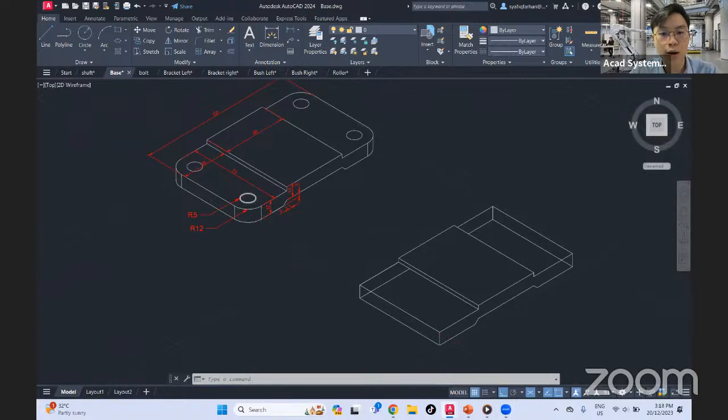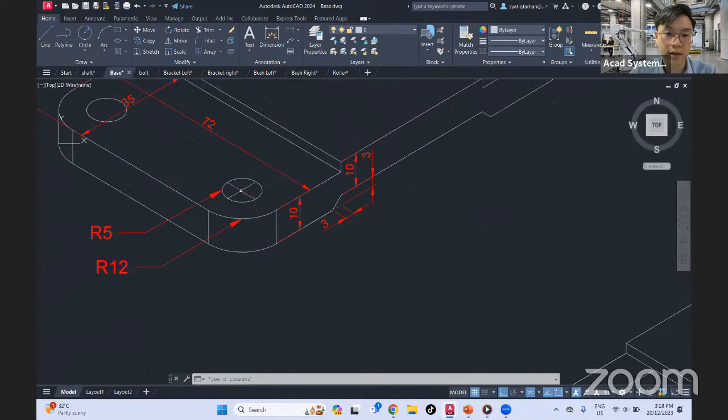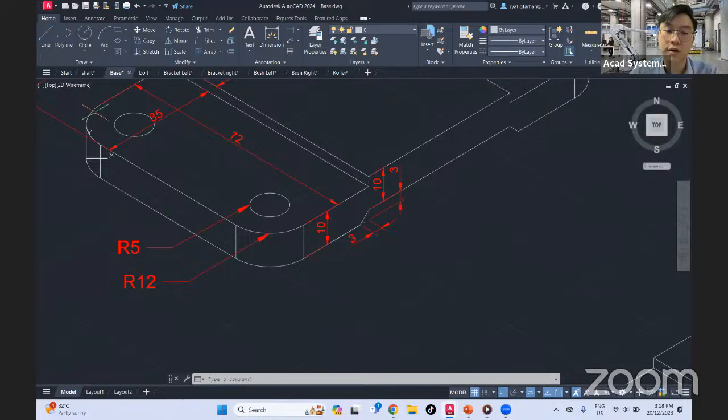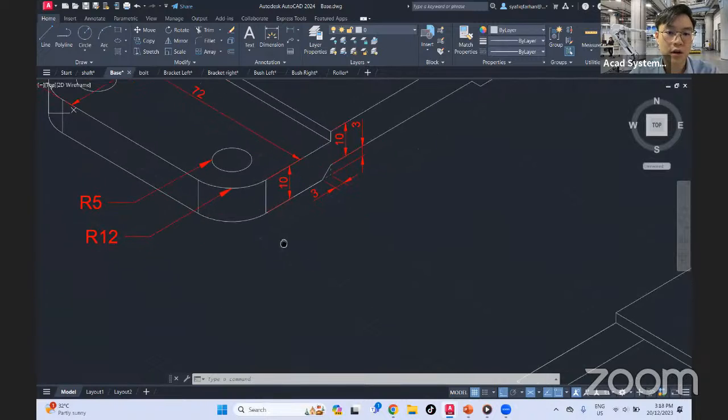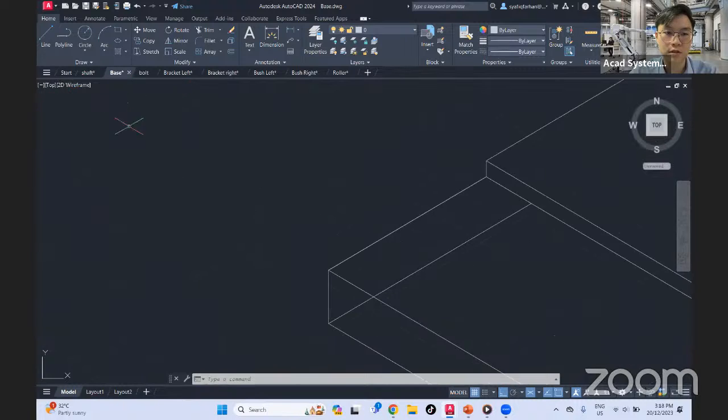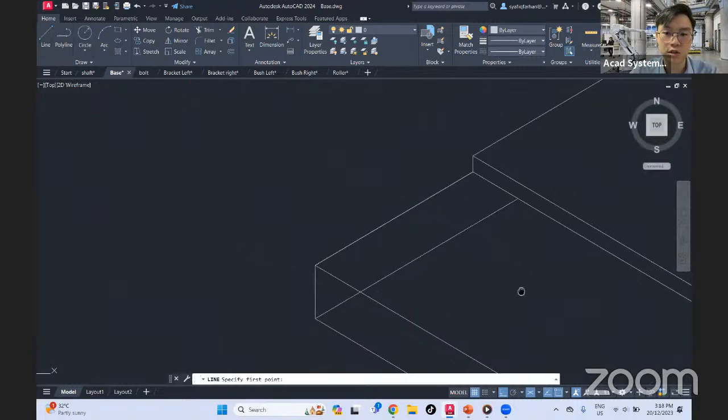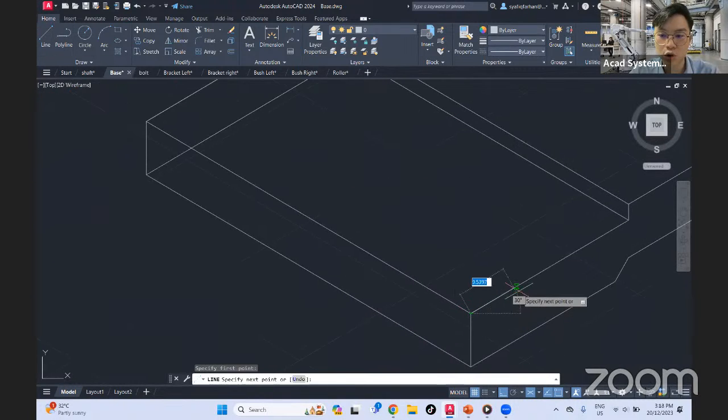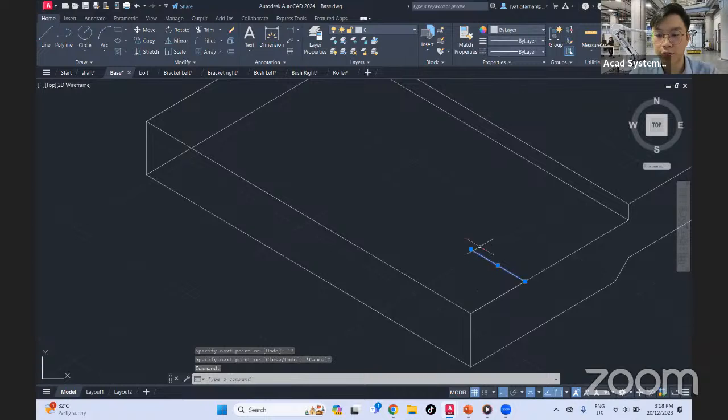But I do not know where the center point of my circle is. Generally, if there is a radius, a fillet, it shares the same middle point. So the fillet has a radius of 12, meaning it's from the corner 12 to 12. To demonstrate, I just need to draw a construction line of 12 and up in the middle 12. So this is the center line. The endpoint of this line is the center point of the circle.